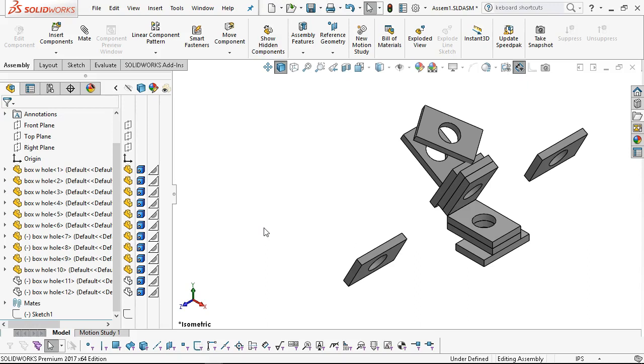The distance per revolution would be 50 thousandths. If you're dealing with metric, the second number is the pitch. So an M6 by 1 thread will have 1 millimeter of distance, and instead of revolutions per inch, we would just go to the distance because it's going to be easier than trying to back calculate.